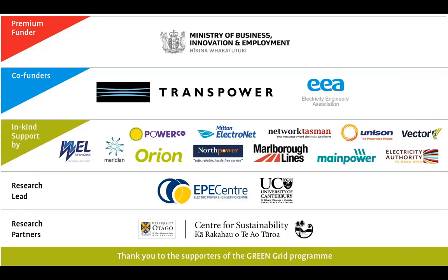You can consider them separately, but the issue is that if you're an EDB, an electricity distribution business, sometimes you change the buck boost of your transformer. You either put your voltage up if you think you've got high loads, or you put it down if you've got lots of PV. The problem is that generally these are statically set, they're not online changes. So if you want to solve the problem for both, it's quite hard, and they're happening at different times, so they're not overlapping that much.